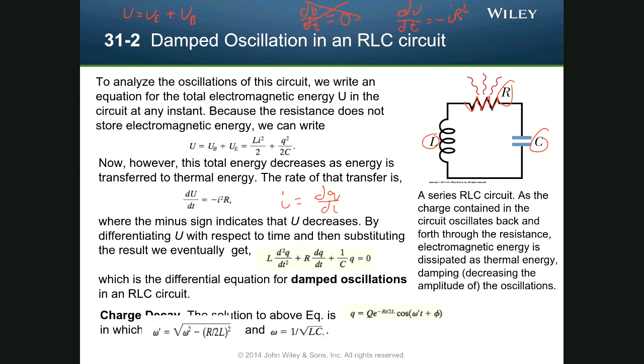and you get this second order homogeneous ordinary differential equation, which you'll notice is similar to what we had before, but now we have a damping term in it, right? So that term will be responsible for the damping, and when we solve it, you'll notice we have our cosine part, like we did before, and we have our amplitude, but we have now this damping part, right? And in this damping part, you can see that as t goes on to infinity, your amplitude shrinks to 0.